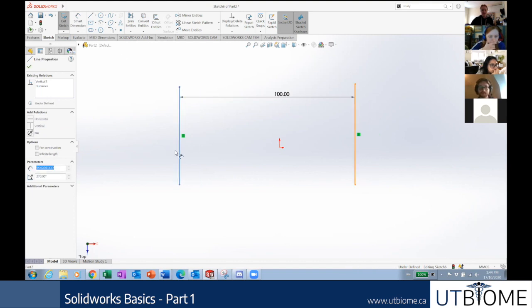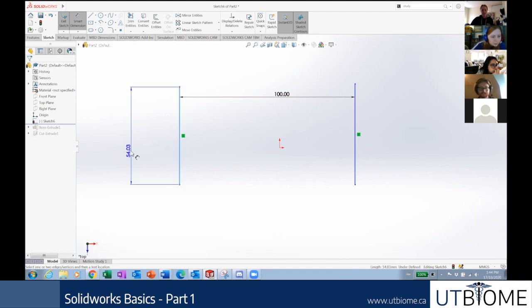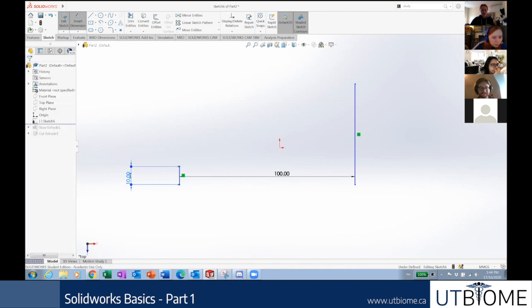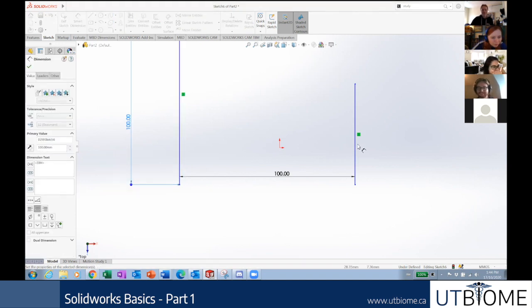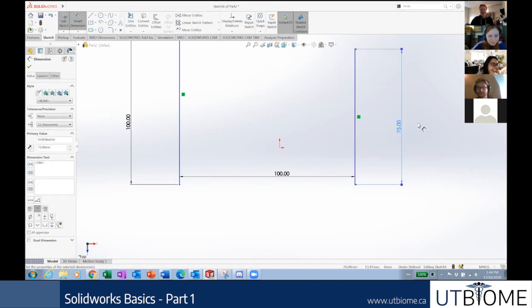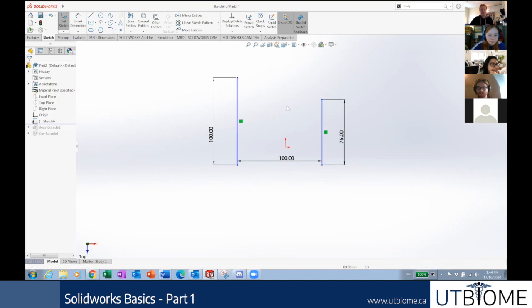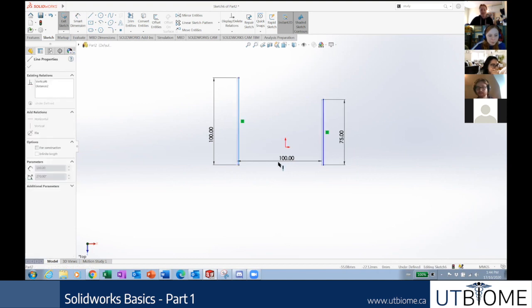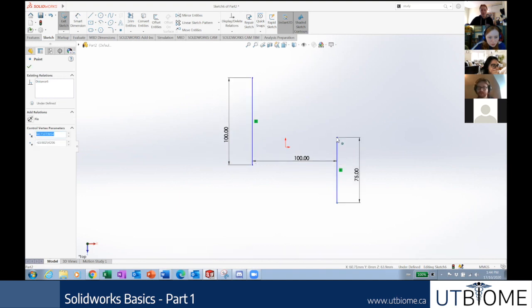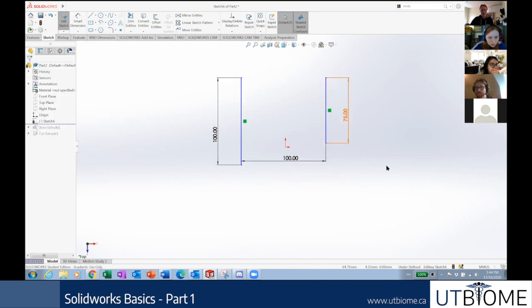Okay, I'm going to dimension the lines too. Say this line. That's pathetic. Okay, let's say that it's 75. This is what people who don't like to use math do. So your lines in SolidWorks stay blue until they're fully defined. We've got all kinds of problems here. They're completely moving. If I was to move forward here, somebody could just hop in here and move stuff around and get away with it, and I wouldn't ever be able to put it back. We like to dimension everything in SolidWorks.